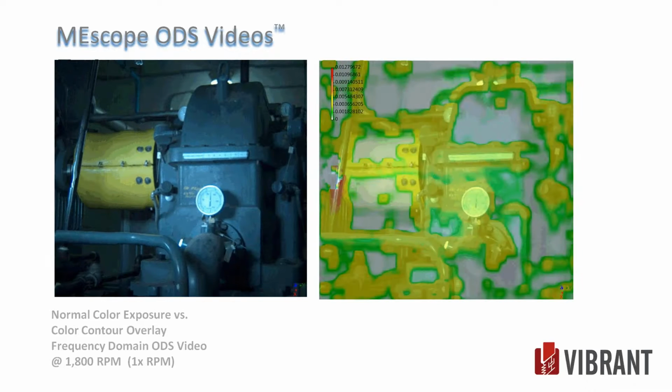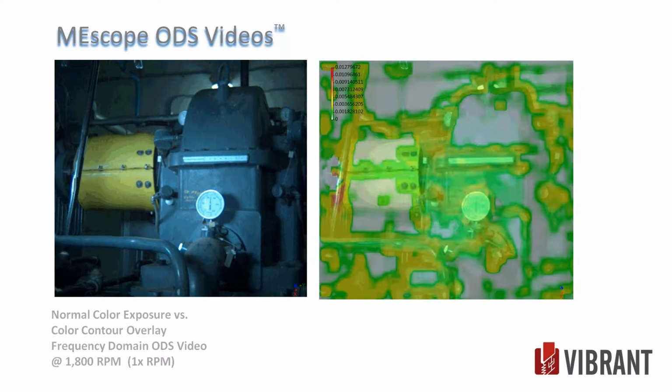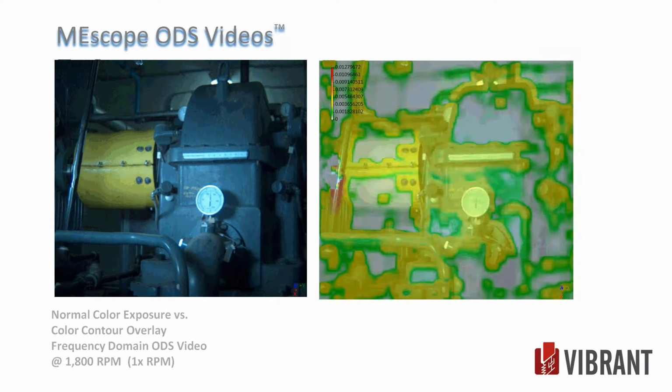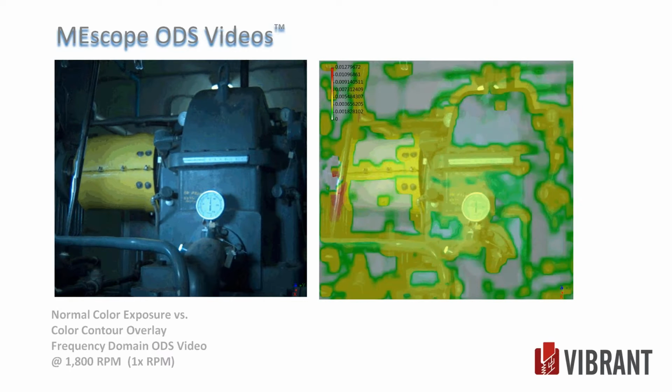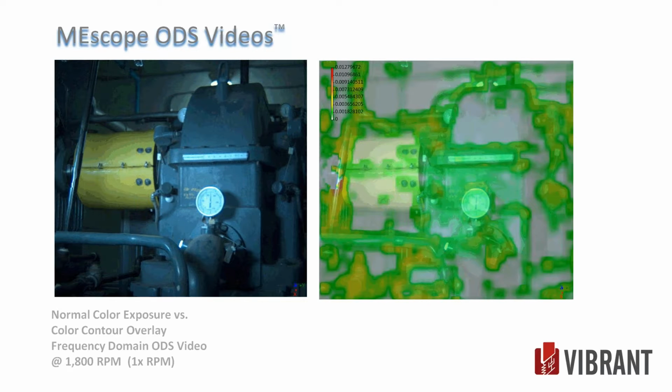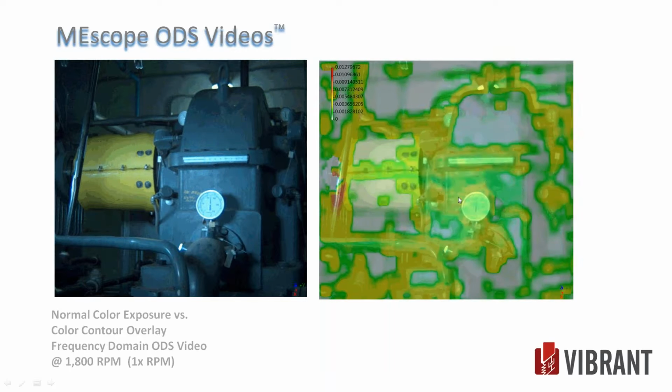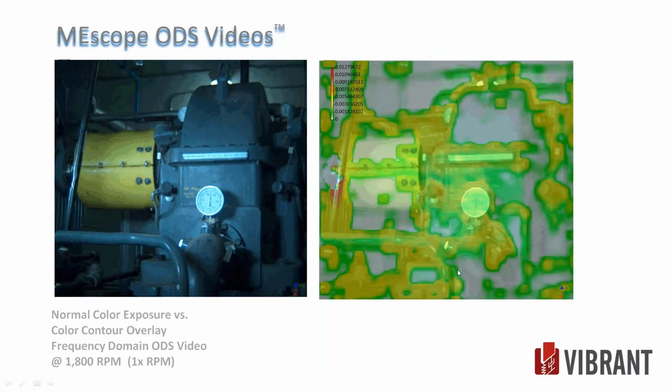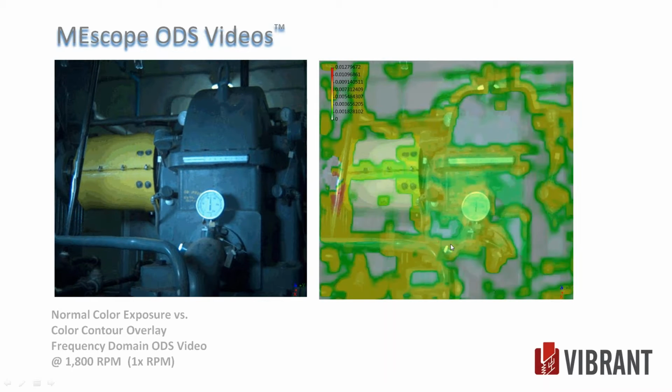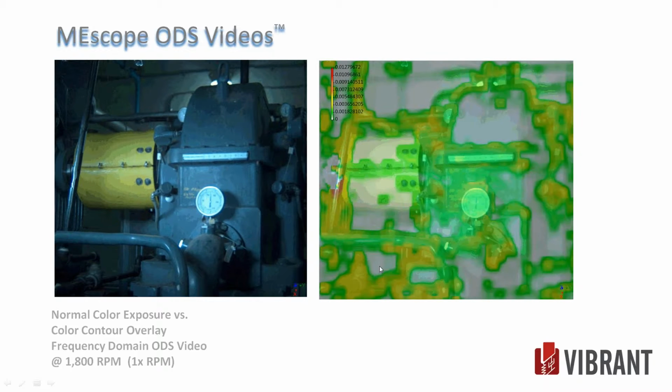This is the gearbox. So the gearbox, you can see everything is bouncing. The generator's bouncing all over the place. There's a little less motion on the gearbox, amplitude-wise, but it's still bouncing. Everything's in phase. I didn't see anything that would indicate a looseness condition or a misalignment.